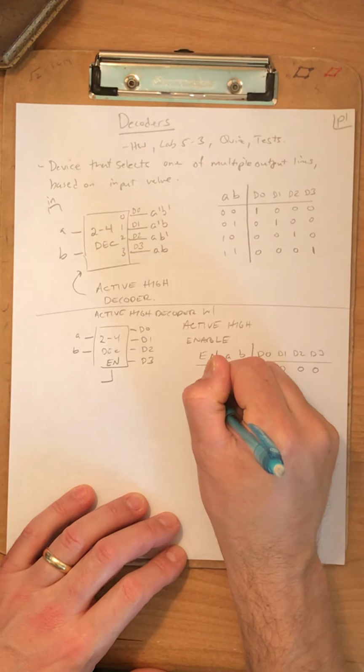We said that this is a min term, A naught, B naught. So think about how you would implement that. There's 4 outputs here. There's 2 inputs. So how would you wire this up? Well, it's just an AND gate. And you also need inverters for here. So A through an inverter, B through an inverter, both of those into an AND gate, and that gives you this. Likewise here, A goes to an inverter, B doesn't. Put them into an AND gate, and on down the line.